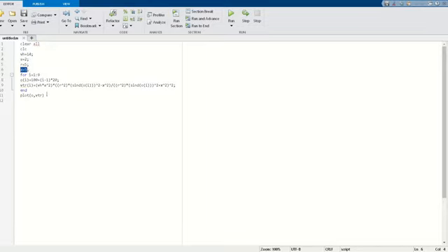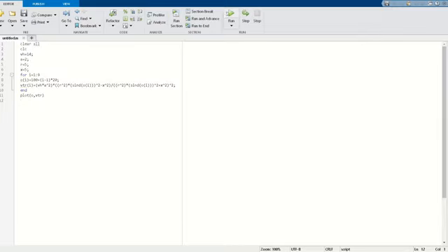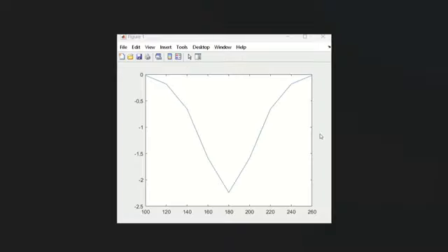From the dynamic equation of tower shadow effect, as you can see in the MATLAB program, we have inserted it in Python so that we can obtain the tower shadow effect. So this is our Python program. After running the Python program, we have plotted the graph of azimuth angle versus tower disturbance shown in the figure.